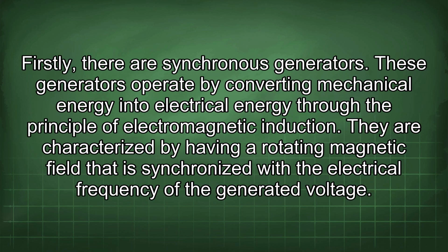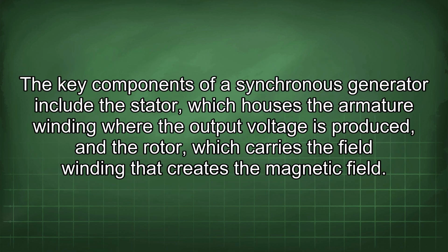Firstly, there are synchronous generators. These generators operate by converting mechanical energy into electrical energy through the principle of electromagnetic induction. They are characterized by having a rotating magnetic field that is synchronized with the electrical frequency of the generated voltage. The key components of a synchronous generator include the stator, which houses the armature winding where the output voltage is produced, and the rotor, which carries the field winding that creates the magnetic field.